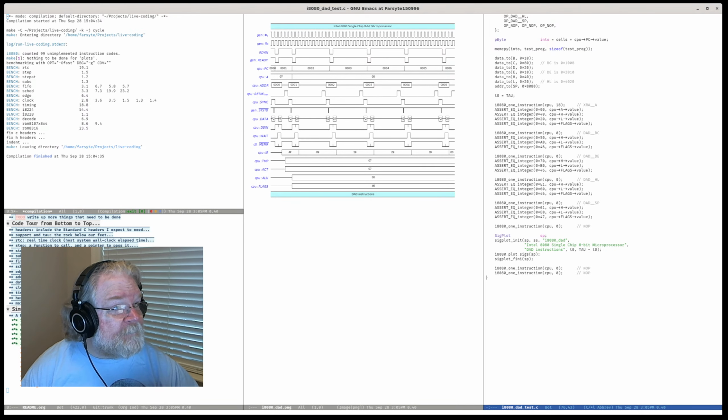But yeah, during M2 and M3, this guy is not issuing status output, because it's not doing any sort of operation. There is no status for internal computation. All the statuses have to do with what kind of an M1 cycle it is, and so on, or what kind of a machine read or write to memory.